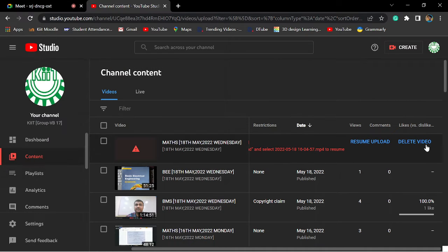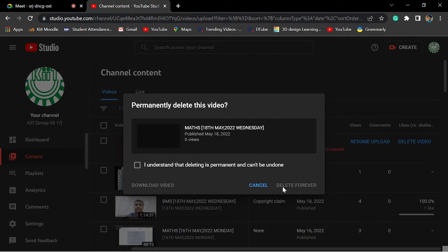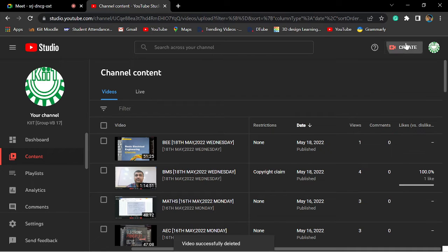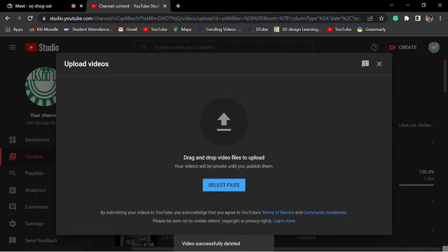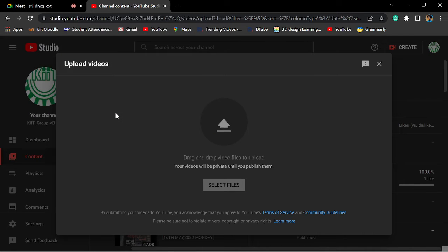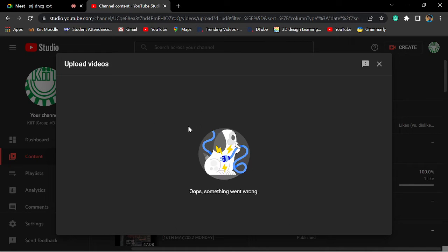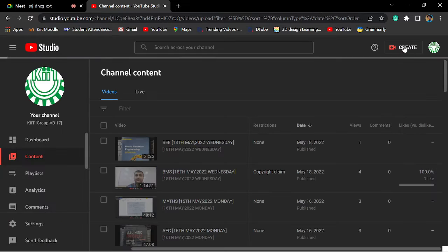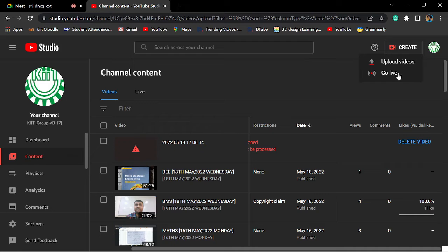So A equals V0 by (V1 minus V2). Ideally A is infinite, or practically it is very high, so the denominator should be 0. That means V1 minus V2 should be 0 or nearly 0. So you can say V1 equals V2.